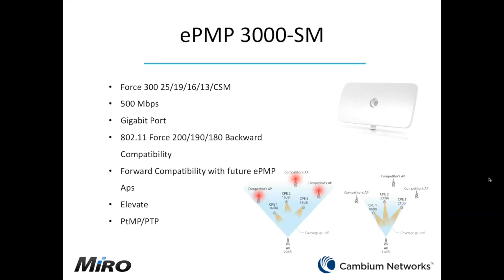I would just like to highlight what you said, Charles. Because we are working in the 5.8 gig band, or the 5 gig band, this is a shared medium, an ISM band for industrial, scientific and medical. So everybody is using it as a free for all. What we don't want to do in this band is overpower and put your radios at maximum power. So if you can choose a radio according to your requirements and let the radio transmit at the dedicated or predetermined transmit power.